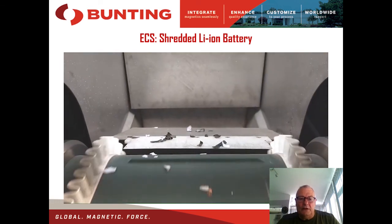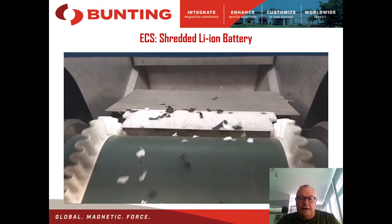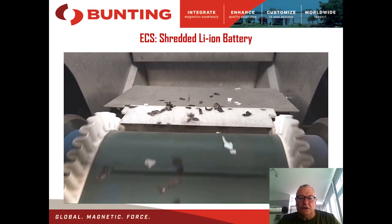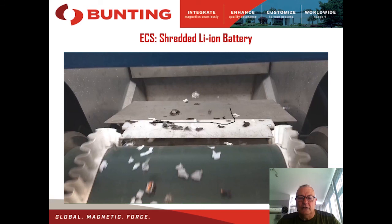As you see, material being thrown from the unit, and mainly our plastic going around unaffected. So here, what I'm doing is creating a concentrate of aluminium and copper cathodic and anodic material, and removing the plastic material for recycling. That anodic and cathodic material would then go for magnetic separation to separate out the anode from the cathode, and then go for downstream processing accordingly.